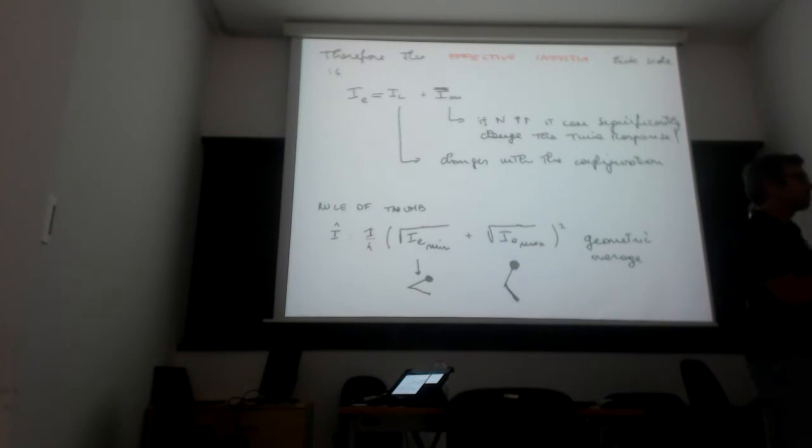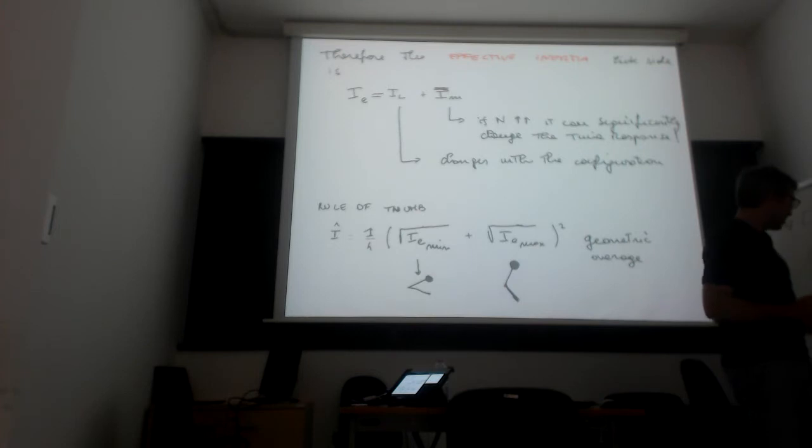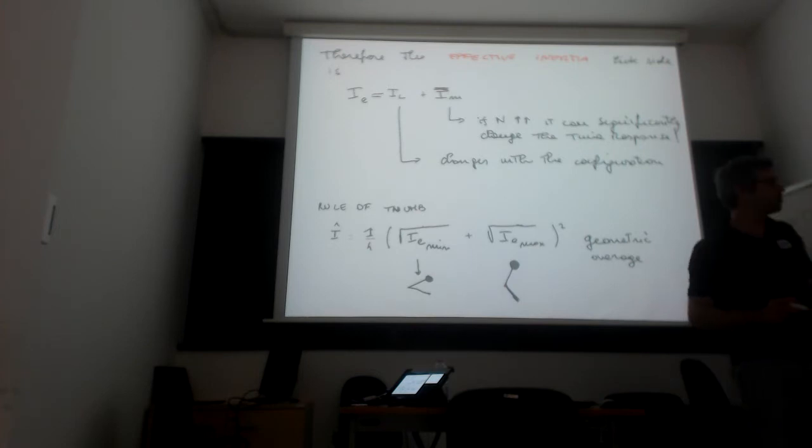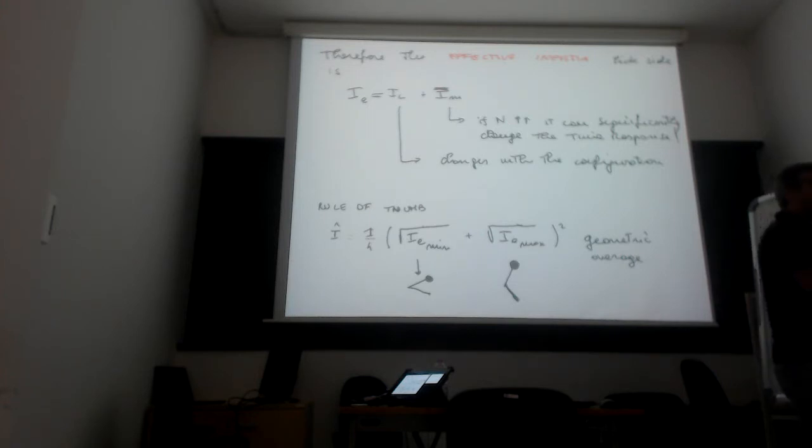Usually in the past we used 100 and 100. Now the new trend is to use a lower gear ratio. Why? Because this way we are able to have faster motion, so we don't reduce the velocity of the motor. We don't lose much velocity of the motor, and to solve the problem of low torque, because now the torque of the motor is only multiplied by 7.